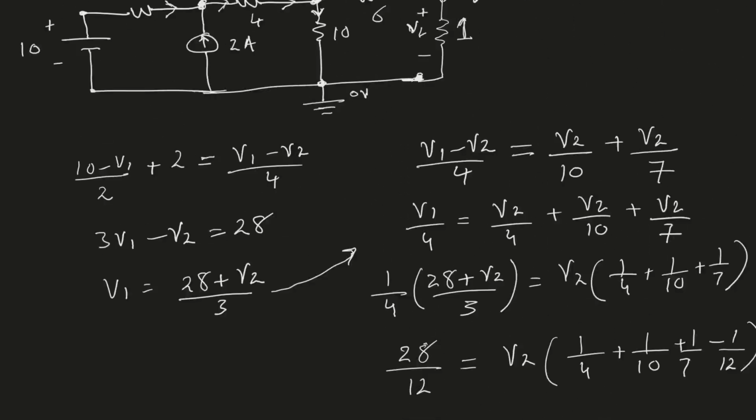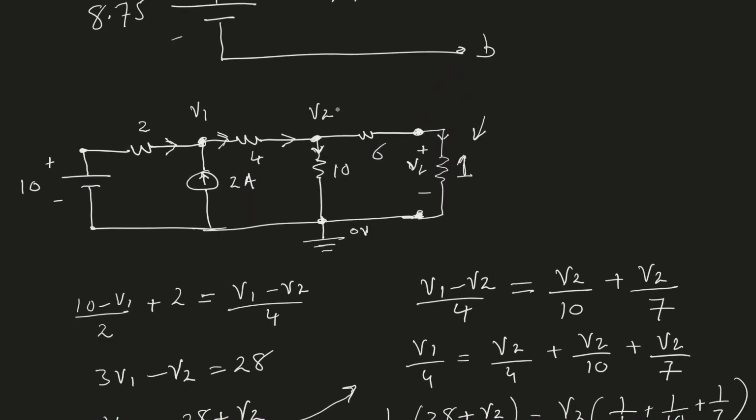And now let's go back to the circuit. I have 5.7 volt here, approximately, and I want to find VL. All right, so now you can see that this is a simple voltage divider. I have 5.7 volt and I have two resistors. This 5.7 volt will be divided between these two resistors depending on their values. The larger resistor will drop most of this voltage, and the smaller resistor will be dropping a small portion of this voltage. So let's apply the voltage divider rule.